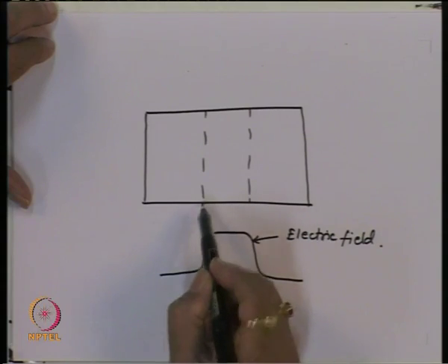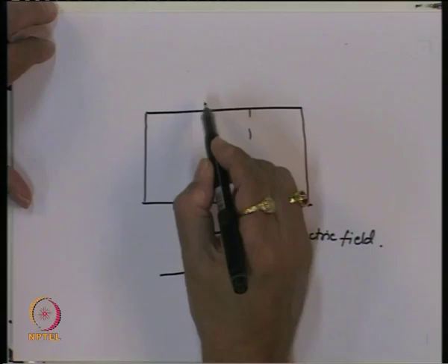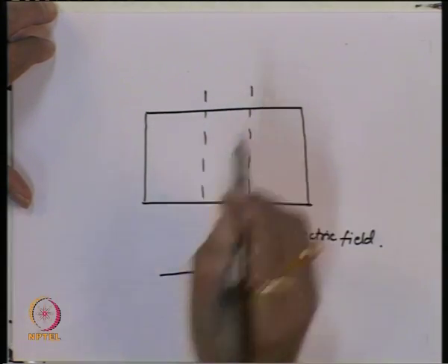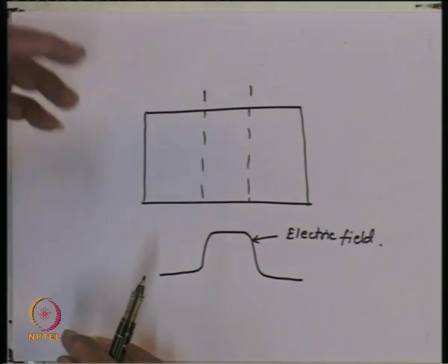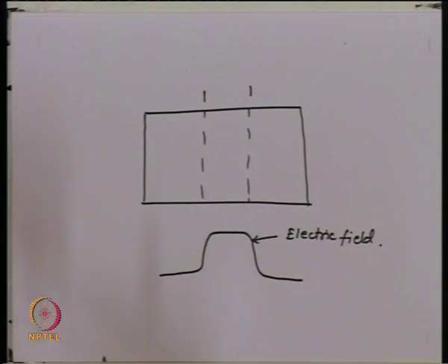The second thing is that if you take a typical PN junction, then the depletion width is of the order of about 1 micron. Whereas if you take the typical absorption coefficient for the material, the effective length over which you will have a substantial absorption of light, which is 1 over the absorption coefficient, will typically be of the order of about 10 to 20 micron.